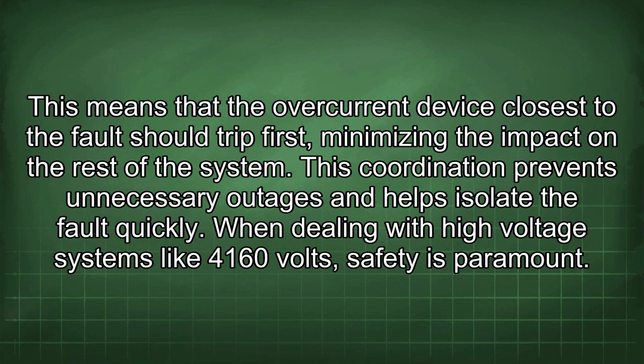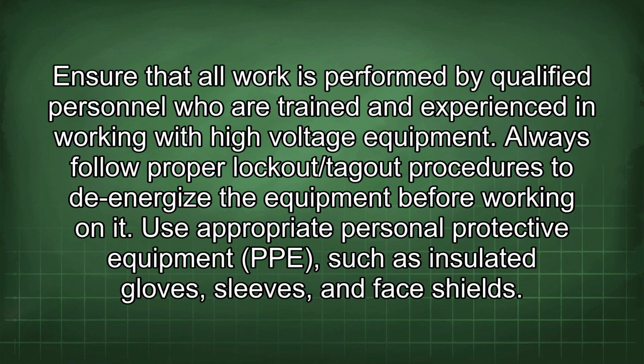This means that the overcurrent device closest to the fault should trip first, minimizing the impact on the rest of the system. This coordination prevents unnecessary outages and helps isolate the fault quickly. When dealing with high voltage systems like 4160 volts, safety is paramount. Ensure that all work is performed by qualified personnel who are trained and experienced in working with high voltage equipment.